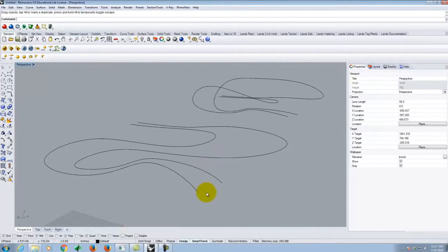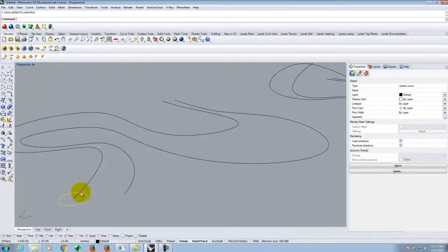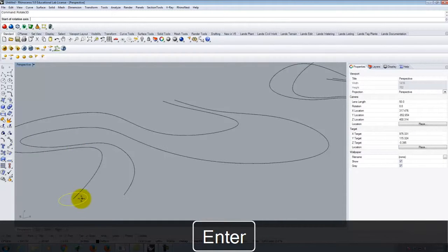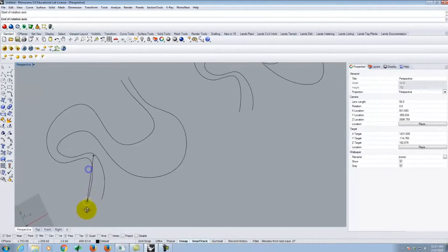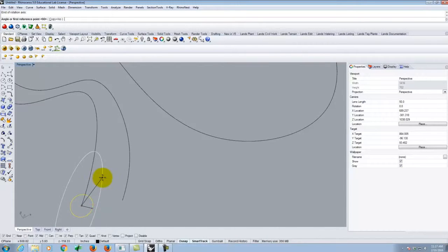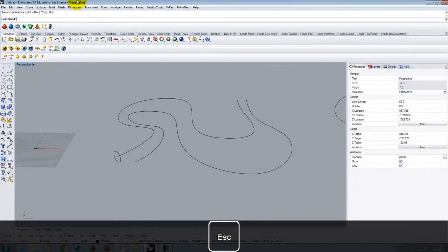Okay? Now, if I wanted to create a tube along this, for example, that would not be a problem. I can start a circle at the center here, and again, my dimensions don't really matter. Now, in this case, the cross-sectional curve is not perpendicular to the curve or even in the right plane, so I do need to do a little quick rotate 3D so that I can make this. Let me do it a little bit more vertical. Right, I'm just trying to put it like that. Okay. Now, I can do the same sweep 1.